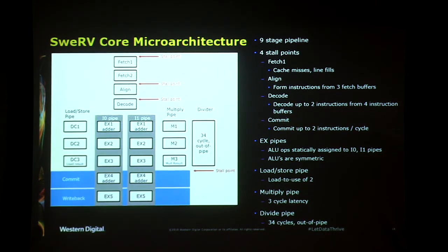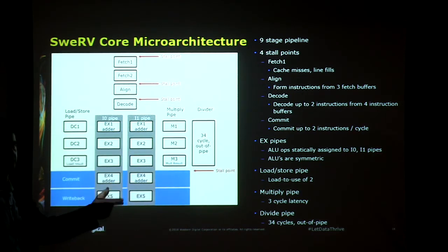And this is how you design your hardware, this is how you design your caches. That works nicely for embedded systems. We have tightly coupled memories for instruction and data caches. We try to fit our code into the instruction cache that we have. And obviously, not everything can fit into our data cache. Sometimes we have a miss and we have to go to the slower flash memory, but that's okay. Your normal latency of 2 clock cycles is nicely handled by the second set of execution units.